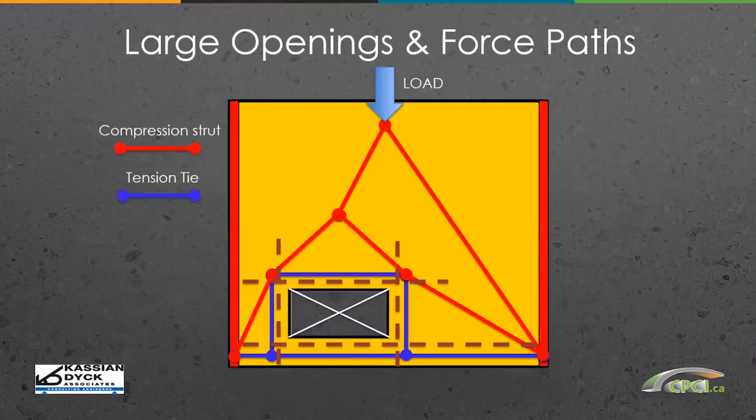I see some engineers just extend reinforcement, the development length past the opening without really looking at what's happening with the whole truss action. You need to look at how the load from the compression is getting into the tension and how that is being transferred, kind of like a strut-and-tie node design. And you really need to make sure you're extending your reinforcement into the anchored zones appropriately to transfer the forces.